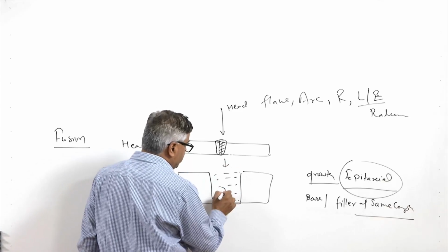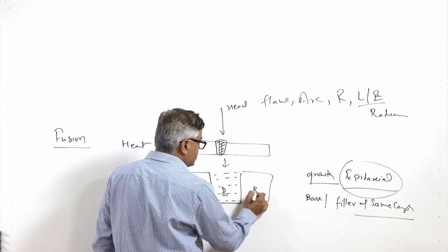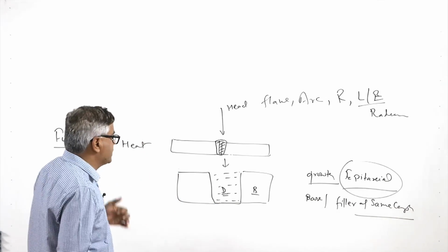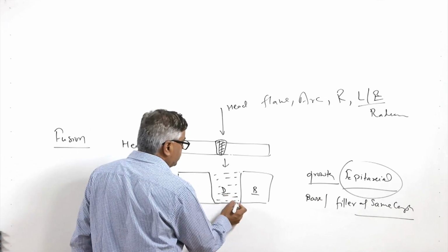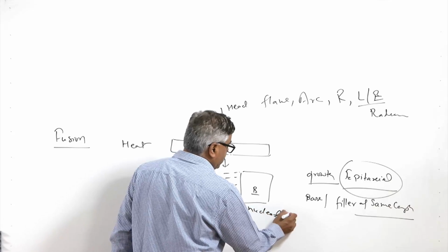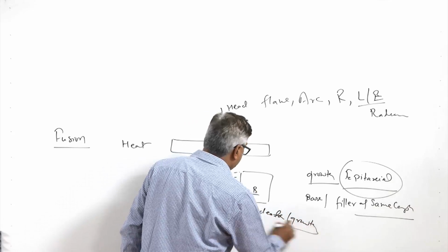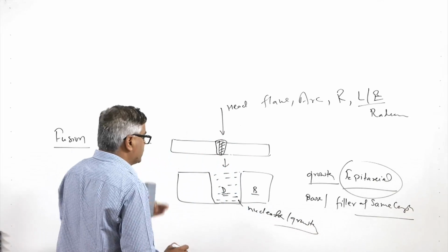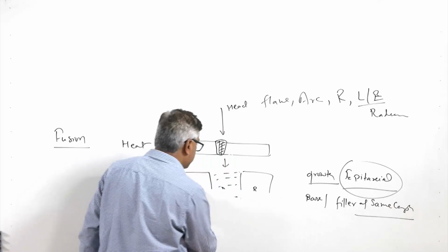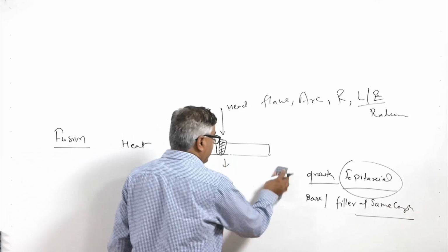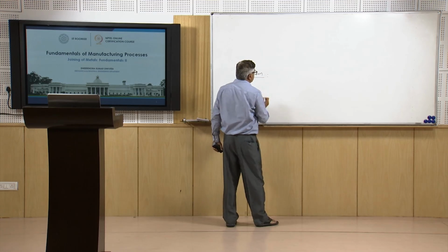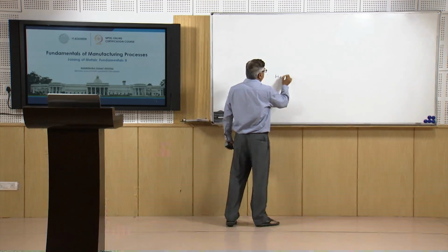So, this is completely different from the base metal, and if it is so, like the crystal structure is different, metal is different. So, that will be leading to the first nucleation and then growth steps for completing the solidification. So, this is called the solidification wherein the nucleation and grain growth both are involved. So this is the role of the heat in the fusion welding.